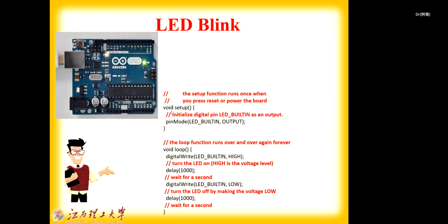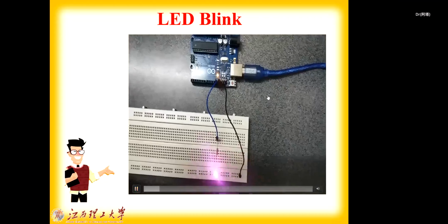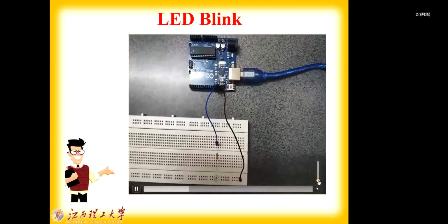Again, we can even review the parts that we need for programming. It's just pinMode, which tells which pin and what its role is. Then digitalWrite, with which I say which value I want to write on that pin. Maybe some of you ask, can we change the pin? Yes, if you change the pin, like in this video, you can simply switch to other pins and also run it, meaning make it on or off. Very simple.